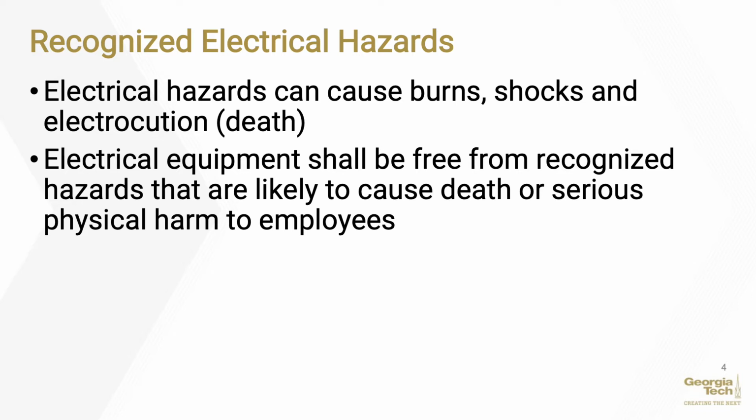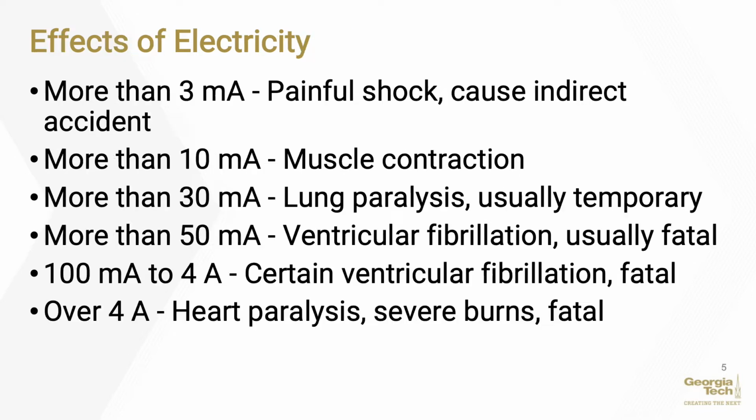Under certain conditions, even a small amount of electric current can result in fibrillation of the heart and death. An electric shock also can cause the user to fall off of a ladder or other elevated work surface and be injured due to this fall. An electric shock can result in anything from a slight tingling sensation to immediate cardiac arrest. The severity depends on the amount of current flowing through the body, the current's path through the body, the length of time the body remains in the circuit, and the current's frequency.